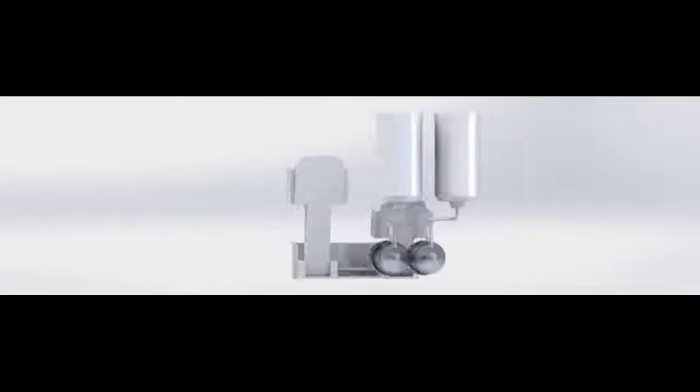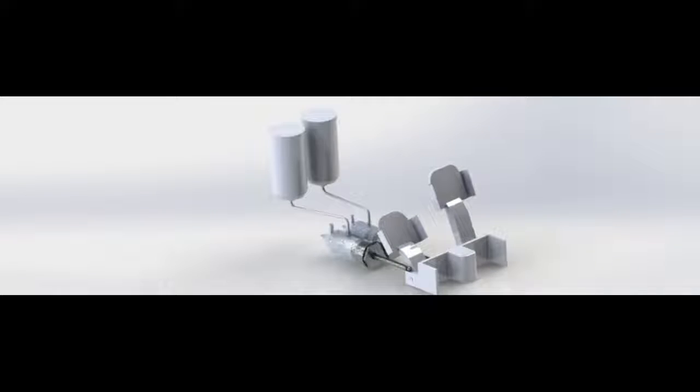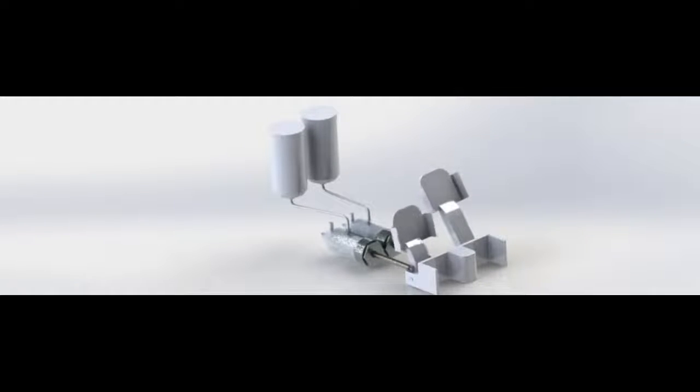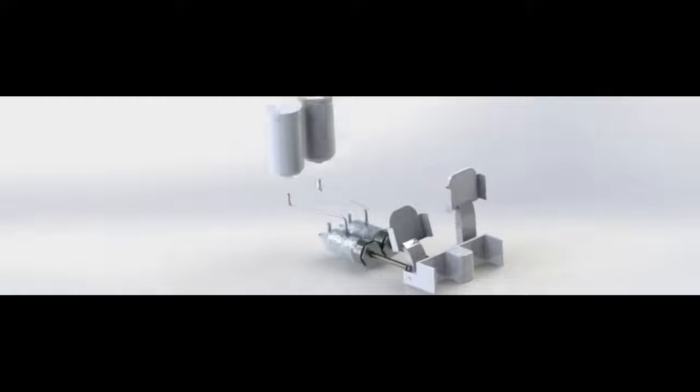Here's the video of the entire brake system, which through the caliper uses pistons to push against the brake pad, against the rotor, and slow the car. In this video we have the pedal assembly with 2 master cylinders attached to the pedals. The master cylinders push fluid towards the braking system to slow the car, and here's the exploded view of the pistons and the reassembly.